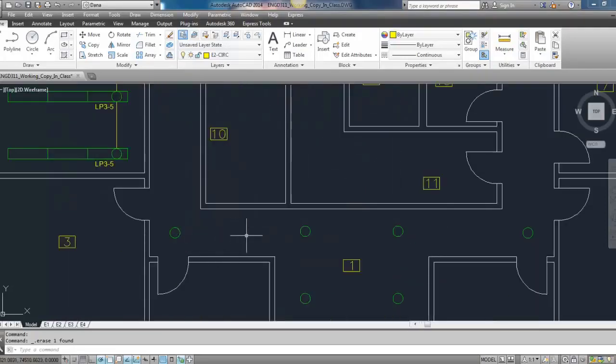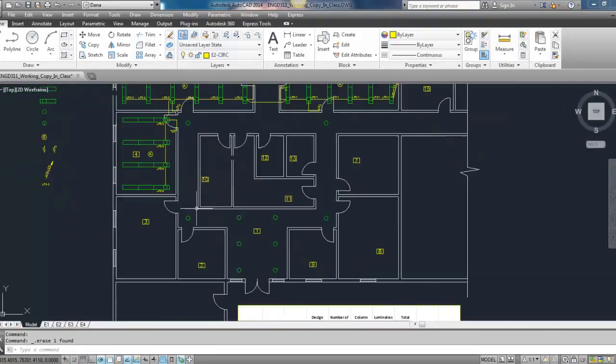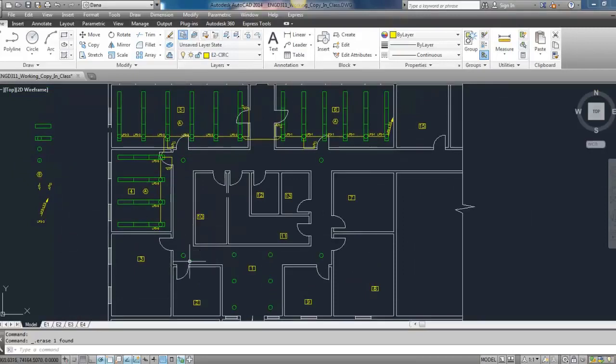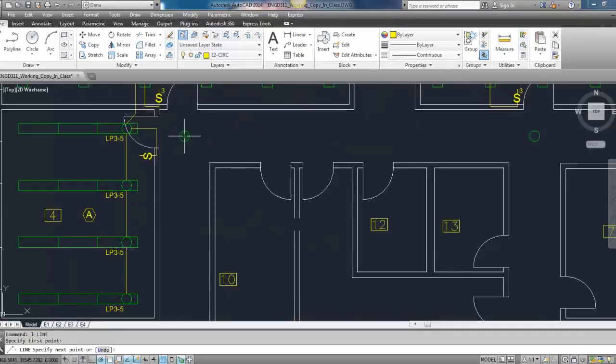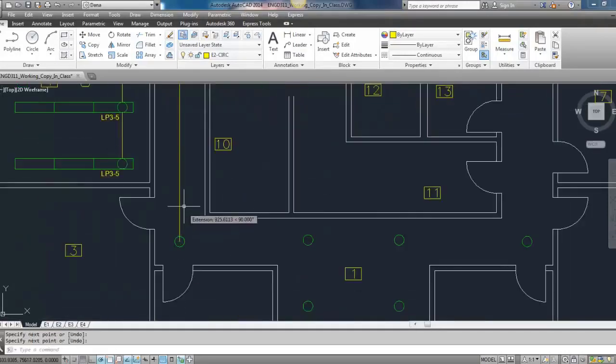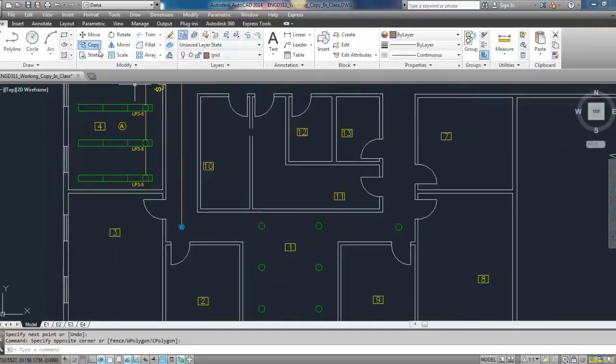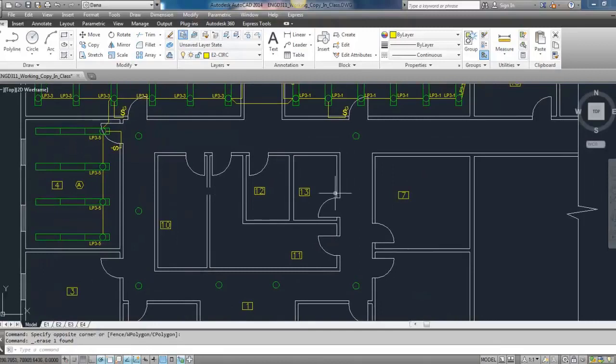Now that makes sense because it will throw light down both sides of the hallway. It's a very efficient way to do it. However, I don't think these lights are powerful enough to throw light all the way down this hallway. So I'm probably going to place another one roughly halfway in between. Now, it's not going to be roughly. I'll be able to get an exact calculation if I draw a line. I'm going to place another luminaire located at about the halfway mark between those two luminaires. Same thing on this side, so really what I can do is just copy this one now that I've done that.